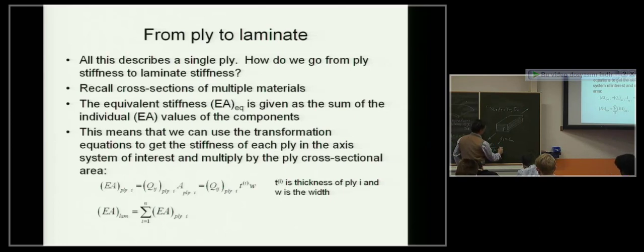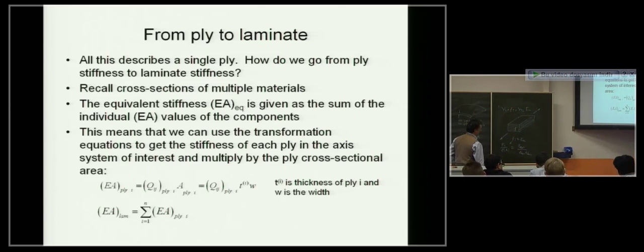So all these are equal to my total applied force, let me call it F total, divided by the E of the laminate times the area of the laminate. By the way, the area of the laminate is just this cross-sectional area here because I'm applying the force in this direction applied on this surface.